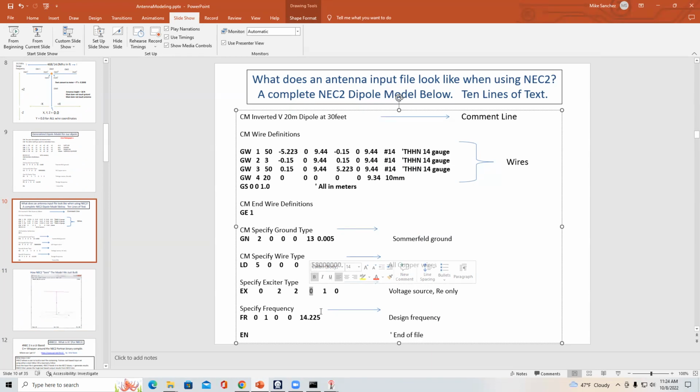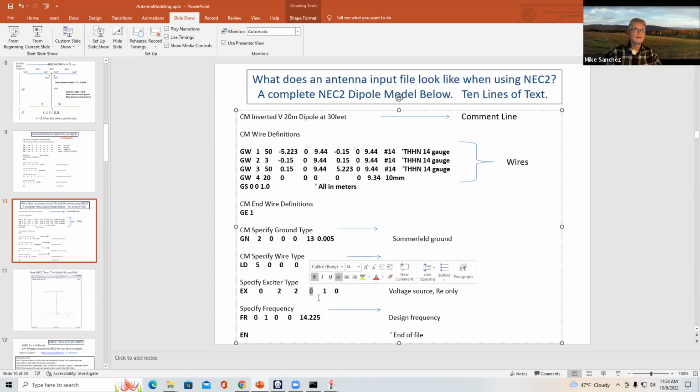The option for column 19: one is maximum relative admittance matrix asymmetric for source segment and network connection will be calculated and printed. So it's the long version of what we found on that help document. And zero means no action, which is what we are using. Very good. Thank you, Hans.